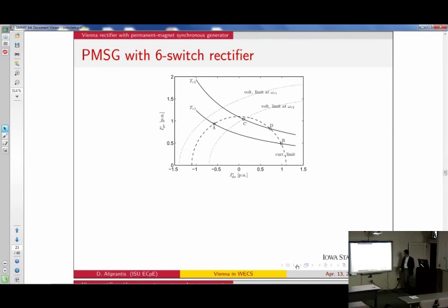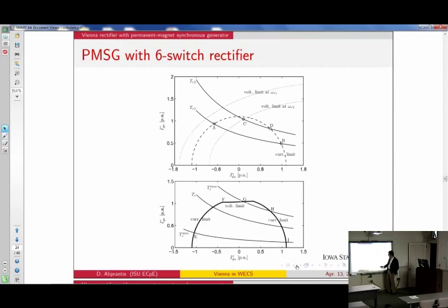So the idea is that we can plot a lot of these curves and do this analysis and figure out our limits for any wind speed. And so you get a plot that looks like that. So this is the feasible operating range of such a turbine. For example, for this minimum torque, I can get this minimum torque if I put any combination of IQ and ID currents on this line. For this torque, for that torque, I can do like that.